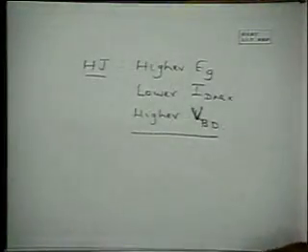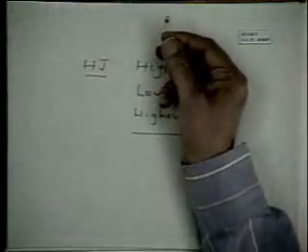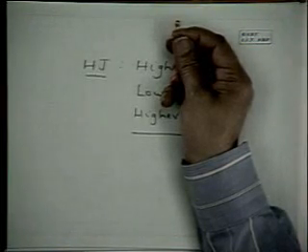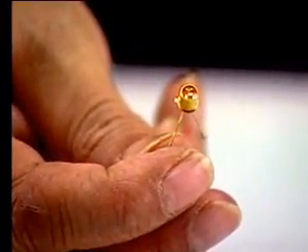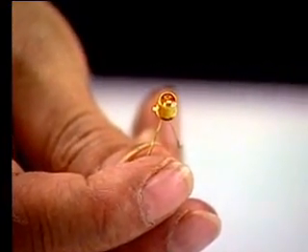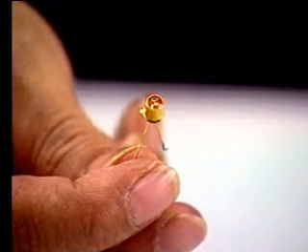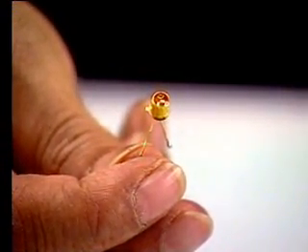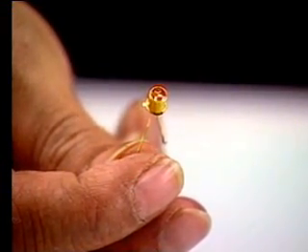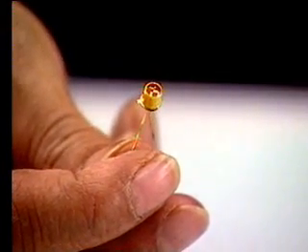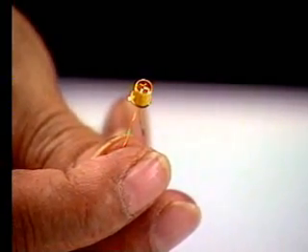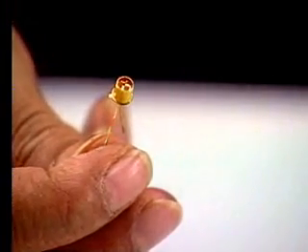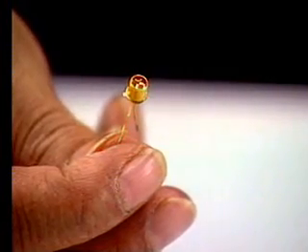If you are interested in optical fiber type of detection, then you have very small devices of this type, which has a lens which can collect light and focus it onto the active area. One of the great advantages of small devices is, of course, the area being smaller, the capacitance is smaller. So the response speed is not only limited by the transit time, but it's also limited by the capacitance. For an optical fiber detector, the central area is just larger than the inner diameter of the fiber. It could be 20 or 30 microns. And the capacitance in that case is of the order of less than picofarads.